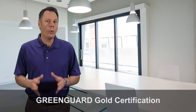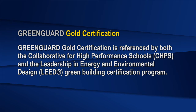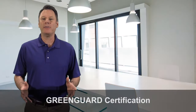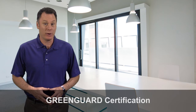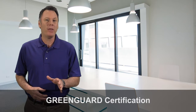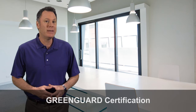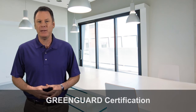The Green Guard Gold certification is referenced by both the Collaborative for High Performance Schools, CHPS, and the Leadership in Energy and Environmental Design, LEED Green Building Certification Program. Any architect, builder, or developer who includes Green Guard certified products in commercial, institutional, or multifamily housing projects may qualify for points toward LEED 2009 for commercial interior certification in its Environmental Quality EQ 4.5 section.